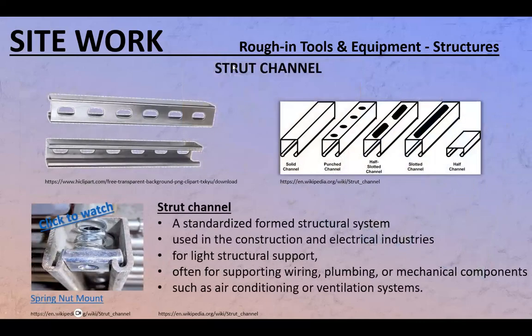Strut channel. What is it? A standardized formed structural system, such as this here. That's what the struts look like. Used in the construction and electrical industries for light structural support. You can actually make a cable tray out of that one. Right? Not a very efficient way of doing it, but you can.